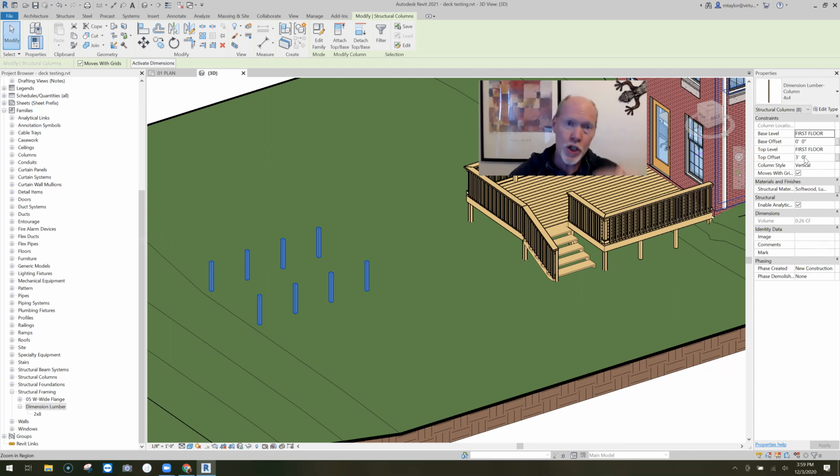Well, you can change the height of these right here and now. I would like the base of them to be 3 feet down. So I'm going to say minus 3 feet. And the top of them to be level with the floor, 0. Okay, that makes sense. And so they shift. So here we are, shifted. Simple enough. I'm going to go back to my plan.